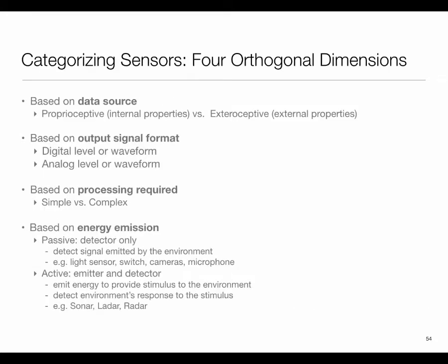The main thing which comes up when we are looking at sensors is, firstly, are they internal or external? What is the output signal format? Very loosely, you would see sensors being referred to as analog or digital. Analog signals send out some sort of analog waveform, and you need to digitize them. Digital sensors already have some processing inside them. They usually will talk I2C or SPI or something like that, and then give you a digital output.